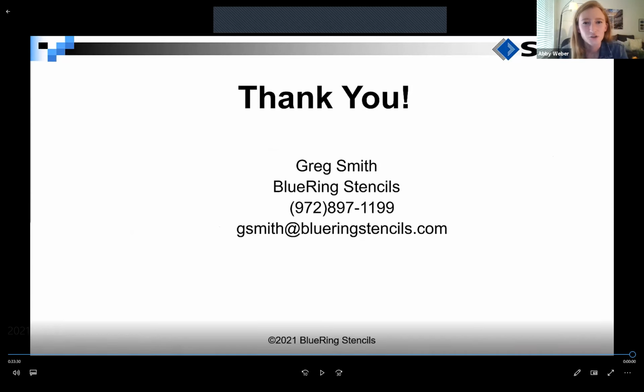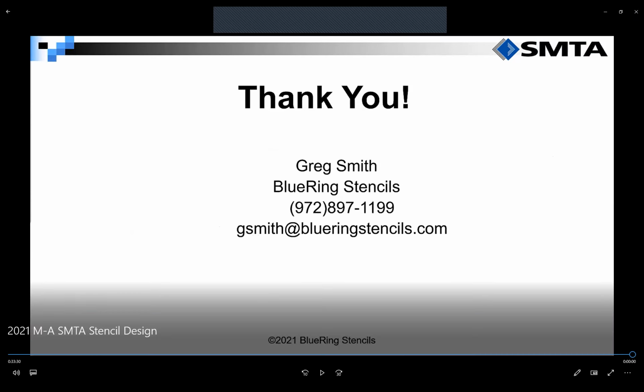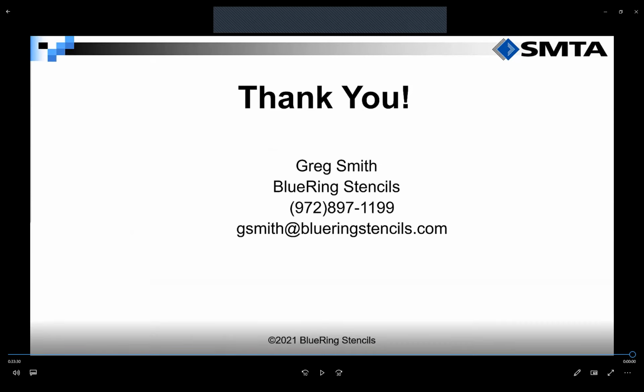Dave asks, do U-shaped stencil apertures cause any release issues? No. Whenever we apply a specific design, like in this case a U-shape, we always still have to look at the area ratio. As long as we maintain area ratios, if it's an uncoated stencil above 0.6, then we should be good. But especially if you want to start applying a U-shaped aperture to an 0201 type component, it becomes really critical to maintain the area ratio in that printability area.